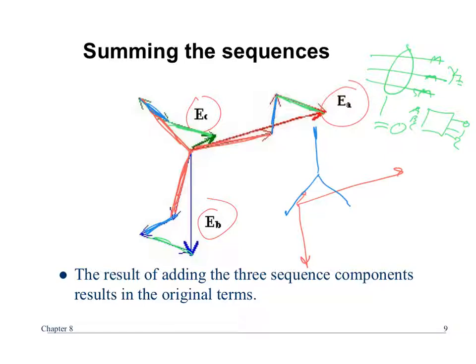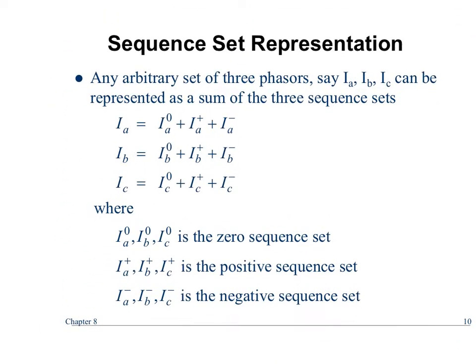Okay? Am I boring you getting off on all these side things? Because I'm trying to set you up for interest in the future. If you're going to be working in the test arena, and some of you may perhaps be doing it, understanding these symmetrical components is important, because the actual test equipment can inject phase currents based on, I need a negative sequence component of this, I need a zero sequence component of that, because that's what you've set for pickup values. So you have to understand why you are setting this negative sequence value, and then the phase currents come out. That's an important activity that you need to do.